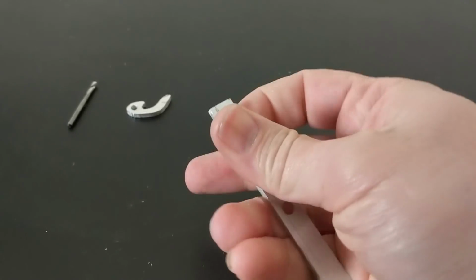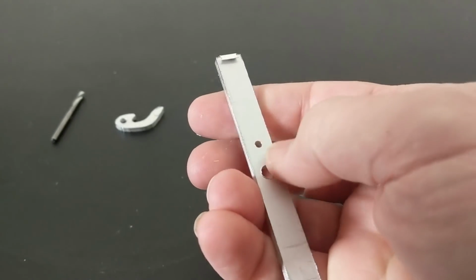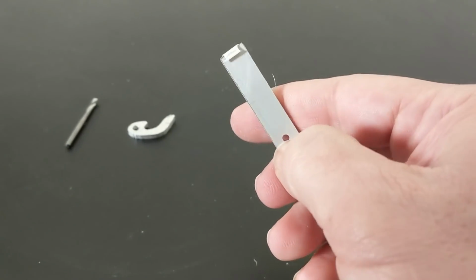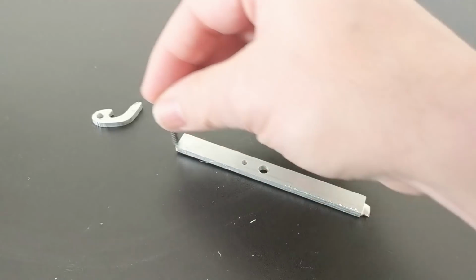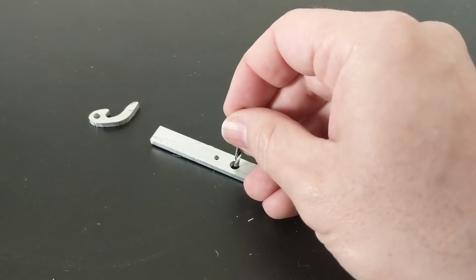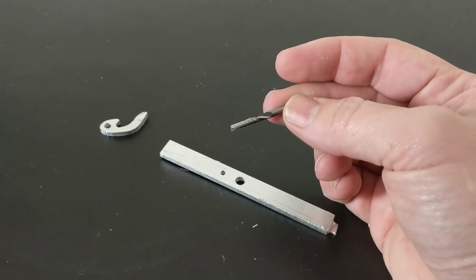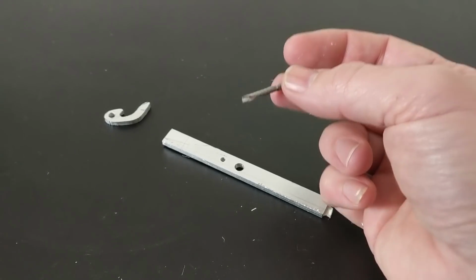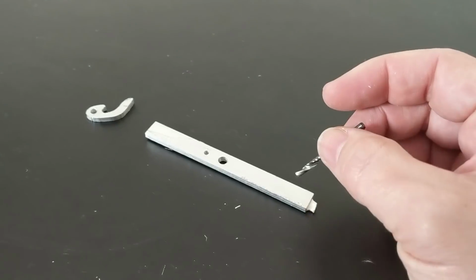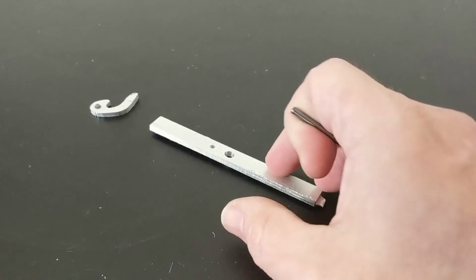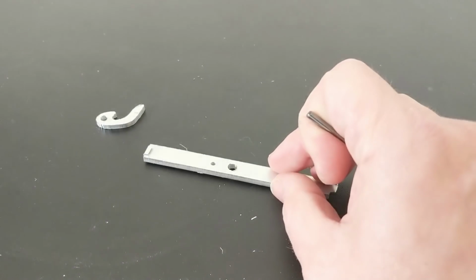But anyway, you can see there's other burrs around the cut, so there is some cleanup to do. And the interesting thing here is the fact that that hole right there is smaller than the bit itself. So this was the bit that I used to cut all around the perimeter and do that central hole, just like that. But for the other hole there, I actually used a smaller bit, a 2mm instead of the 3mm bit here. So I was able to do a bit change in the middle of the cut job and get that hole drilled. So that means that I can accomplish everything I want to accomplish as far as cutting out the geometry to finish mounting that motor to the frame more securely than with a 3D printed part.